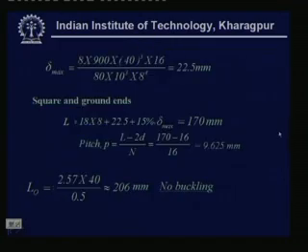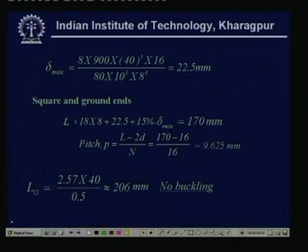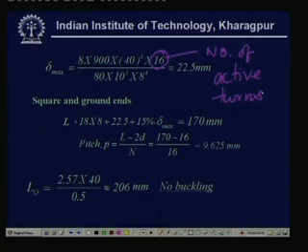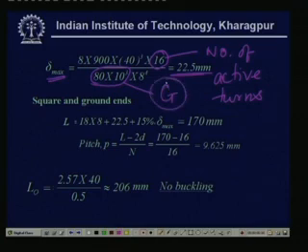Okay. So, this comes out to be the case; this 16 is the number of active turns. Once we get the number of active turns, we have found out the maximum delta. This is the deflection of the spring, which comes out to be 22.5. Please note that we have assumed 80 into 10 to the power 3 MPa as the value of G. This is nothing but the value of G for steel material, which can be assumed.